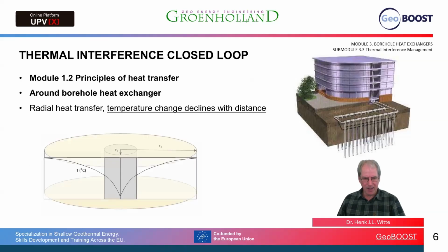I will look mainly at the methodology as we have developed it in the Netherlands, and that is based first of all on the principle of heat transfer around the borehole heat exchanger that we already discussed in module 1.2. The basic idea here is that the further we move away from a particular borehole heat exchanger, the smaller the temperature change in the ground will be.